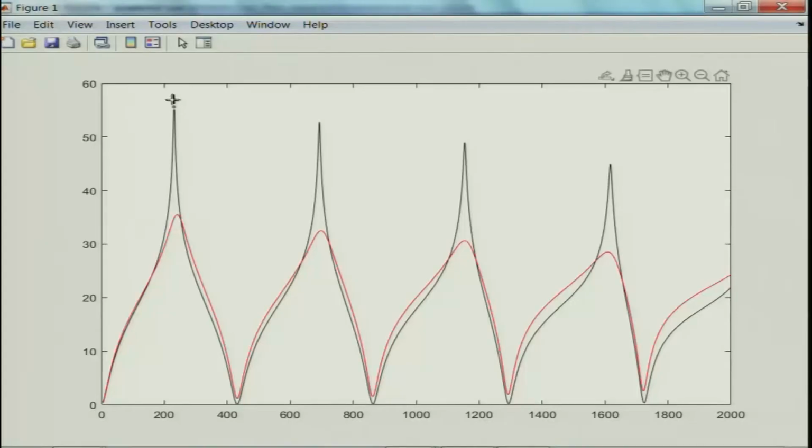for flow reversal configurations we really have end corrections. So, even the peaks that you are seeing here will be shifted towards the right side of the spectrum because of the reduced effective length of the chamber. So, these are all end correction matters. Maybe we can discuss some of them when we come to the stage of 3-dimensional analysis.